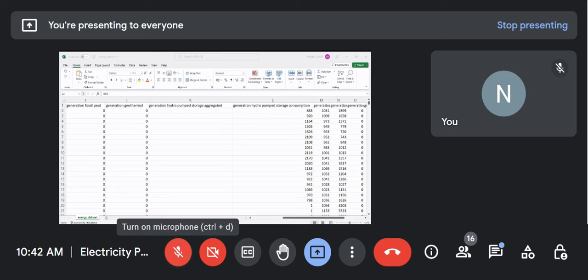Okay, got it. But then again, there is expenditure, right? There is a cost involved in pumping from lower to top. Of course, but it is available at a lower cost, because it is a surplus energy. Okay. Because suddenly there was a reduction in the consumption, the consumer will not pay, but you have purchased it, so the cost is already paid by you. So you are trying to optimize, because the consumption and generation will keep fluctuating.